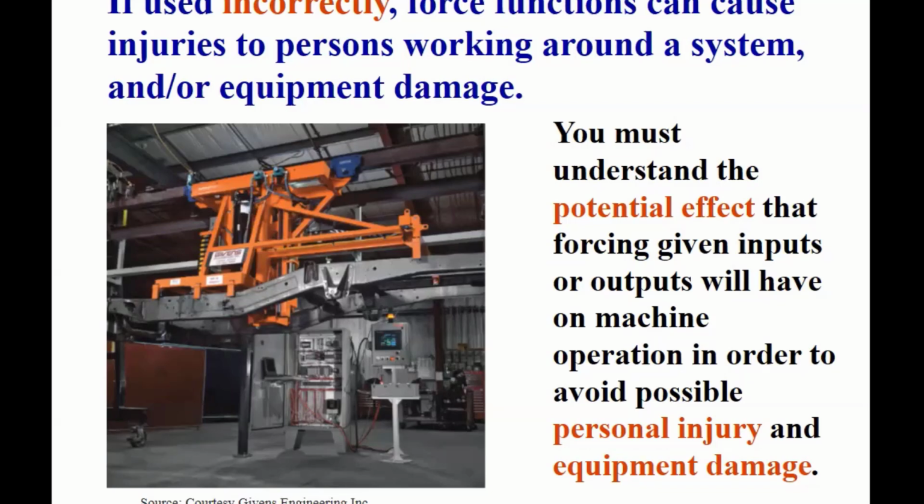You must understand the potential effect that forcing given inputs or outputs will have on machine operation in order to avoid possible personal injury and equipment damage. It's a very powerful, but also dangerous form of program control instructions, right? The force instruction. You've already seen some of that, and it can be disastrous.